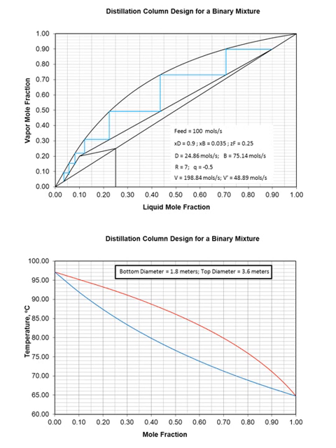Last, we have to determine the size of our reboiler, and so we need to know about the temperature that we have in the reboiler. As we saw before, we can do this by projection of the upper graph down to the lower. And doing it here, we have a temperature of around 95. And so this will be used for calculating the energy balance around the reboiler.